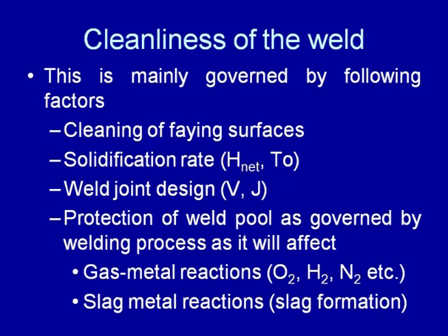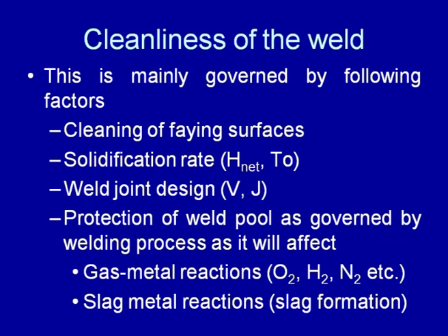Then protection of the weld pool, as per the process which is being used. If the protection is good, then all the gases present in the atmosphere like oxygen, nitrogen, hydrogen will be kept away from the weld pool and their adverse effect can be avoided. But if these are able to reach the weld pool, then it will lead to gas metal reactions, and the gas metal reactions will lead to the development of inclusions and porosity in the weld zone.